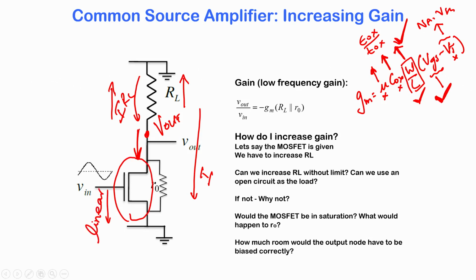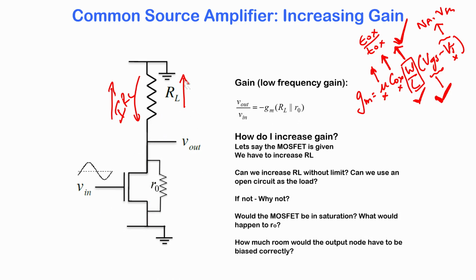Okay, it will start operating in a linear mode. And what is the problem in linear operation? The problem in linear operation when you use it as an amplifier circuit is that any fluctuation in V out will now start pushing a lot of current through this device, because now this device has got a resistance of RO linear, which is very small.